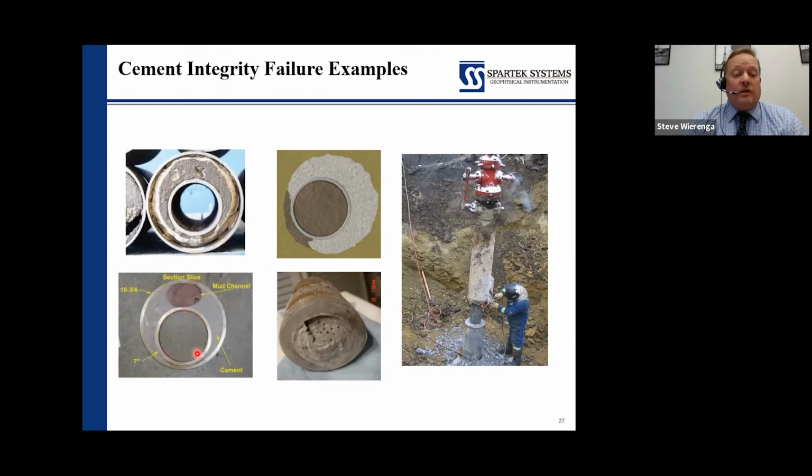We may see this condition here where the pressures weren't managed during the cementing operations, and during the setting process there is a period of time where the slurry is unable to hold a hydraulic cap and hold back those muds. So if we don't have those pressures in place, we can end up with mud being pushed up hole by formation pressures. You can actually see even a little bit of a gas bubble in here. So that would be a very big concern for communication. You can see that they're eccentered here as well. That's probably a big contributor to this condition.